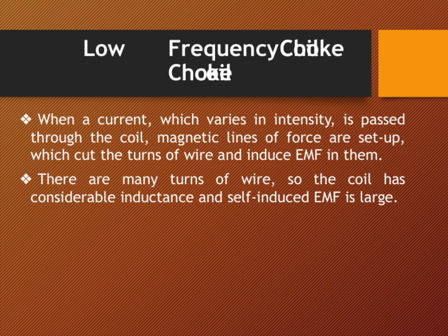This is why choke coils, especially low-frequency chokes, are so useful. They help limit or smooth out changes in current. The large inductance effectively opposes rapid fluctuations in current, making them essential components in many electrical circuits. Connecting this to the overall theme, understanding how coils and inductance work helps us design better filters and energy storage devices. So, in essence, the more turns a coil has, the greater its inductance and its ability to resist sudden